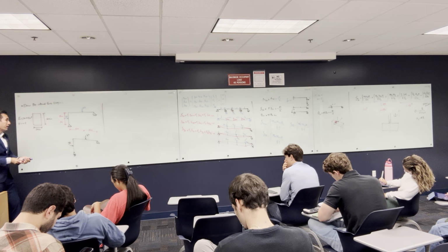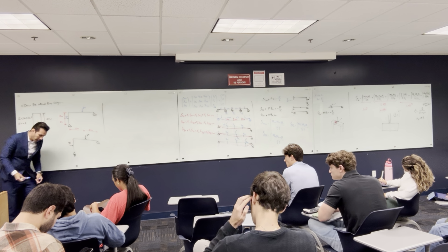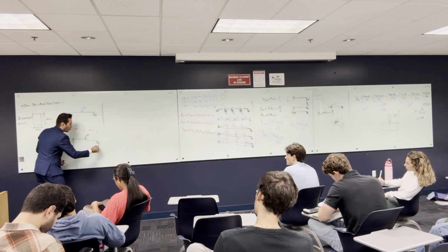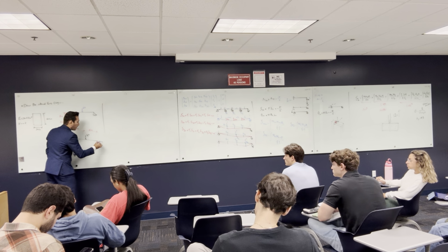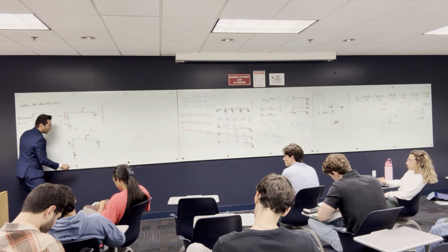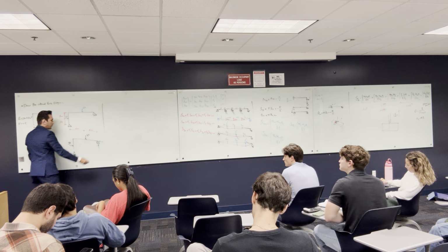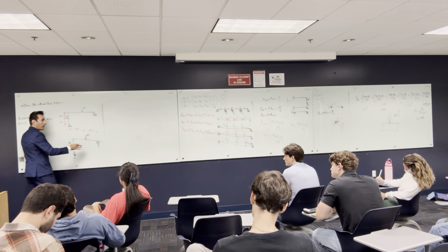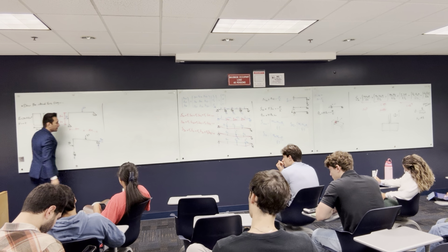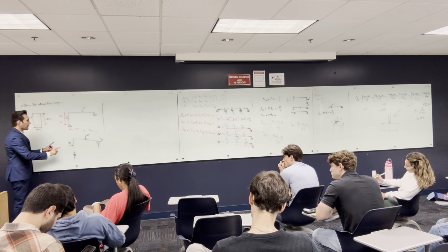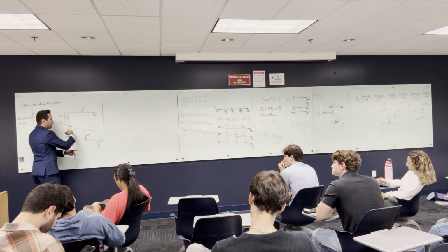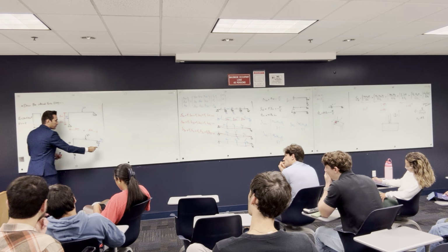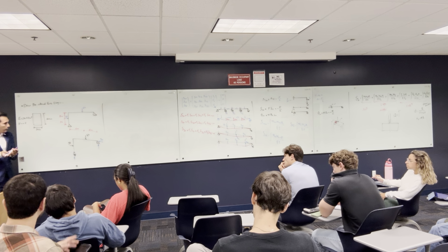What do I mean by solving this main system? You have to find the reactions here: the Y reaction here, the X reaction here, and the Y reaction. The easiest one is this one. What is the value of the X reaction? You have 3 ton here, and the only way to resist it is with another 3 ton. This 3 ton is going to make a moment that way, and this 6 is going to make a moment that way. So you have to take the moment here to get the reaction here.